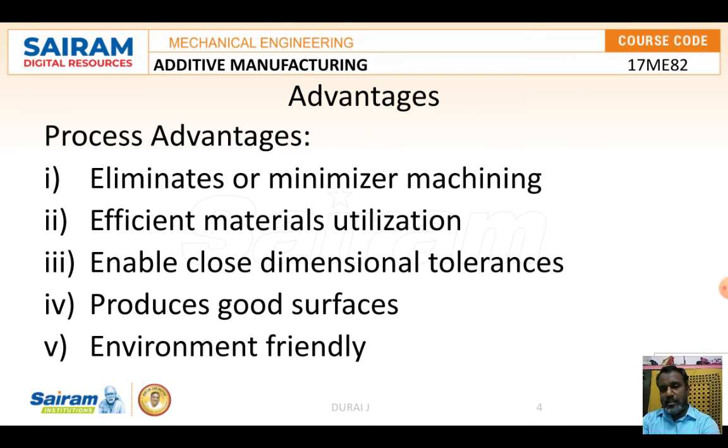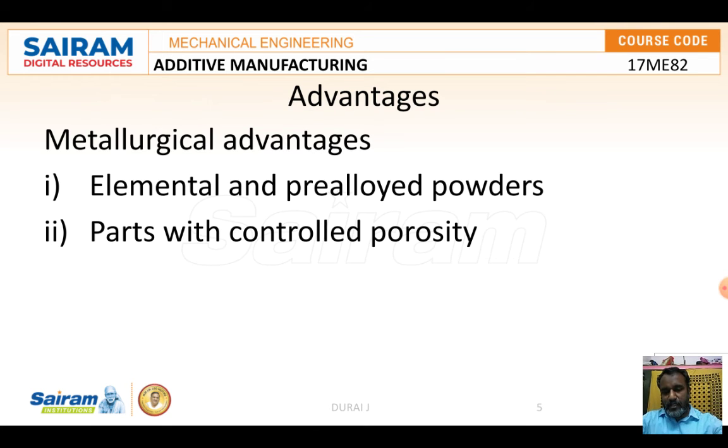If a good die shape is provided, the tolerance and everything will be achieved exactly. With a cutting tool, the tolerance may not be possible to reduce this far. According to the die shape, you can get the exact shape as well as the dimensions in the workpieces, so it has high dimensional tolerance. It also provides a good surface finish and is environment friendly.